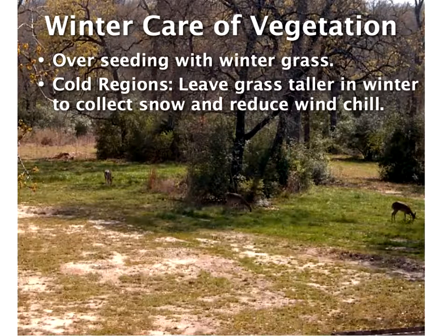Okay, winter care. It's a good idea, particularly in cold climates, to have something growing over the drain field. We want to collect snow. Snow is the best barrier. Whenever we have problems of freezing, and happily we haven't had any for several years, as people seem to have learned how to handle it.